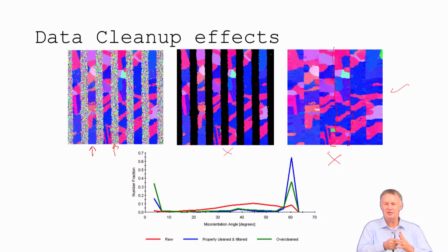confidence index standardization that I've told you about, where it just makes all the points within a single grain, what's defined as a grain, turns all those high confidence so that we can save all those data when we do a confidence index filter. But if you do a grain dilation cleanup or you do an orientation correlation cleanup or any of these, then you can create artificial data.